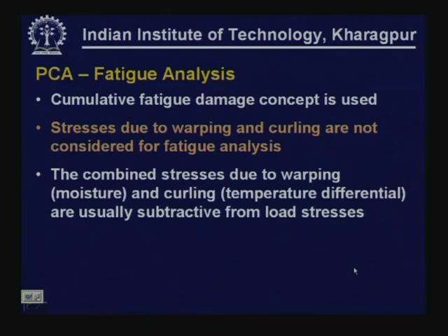Cumulative fatigue damage concept is used in PCA. Stresses due to warping and curling are not considered for fatigue analysis. These stresses are not added to the wheel load stress while carrying out fatigue damage analysis, because both of them happen throughout the year, throughout the life period, so the combination being additive is not possible. Sometimes it is additive, sometimes it is subtractive. So, the warping and curling stresses are not considered and they are not added to the wheel load stresses for